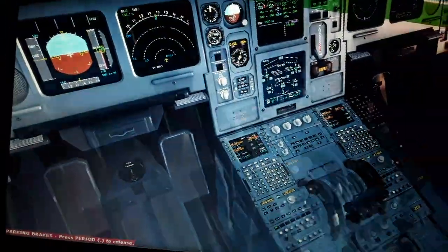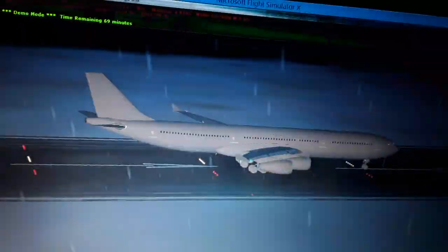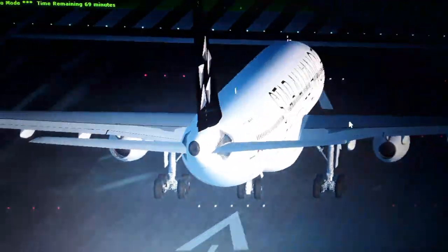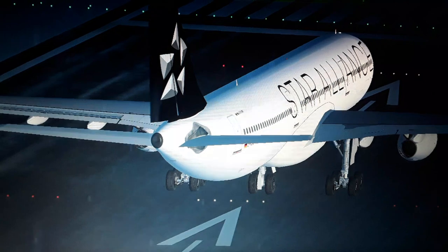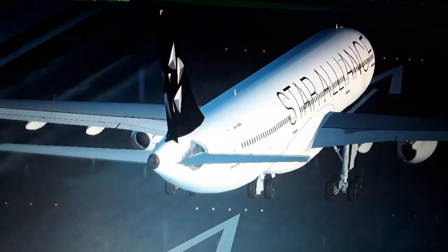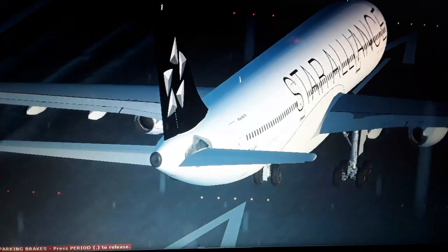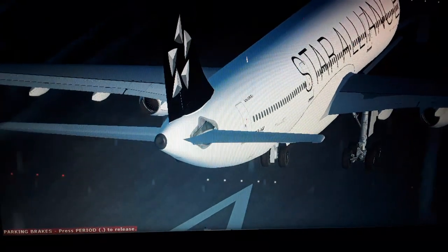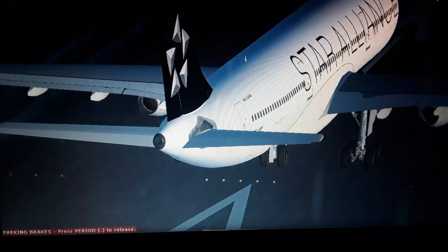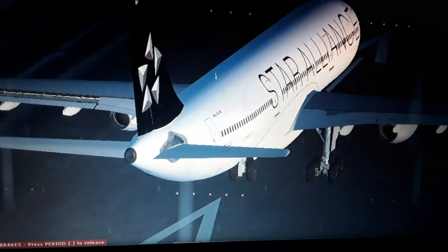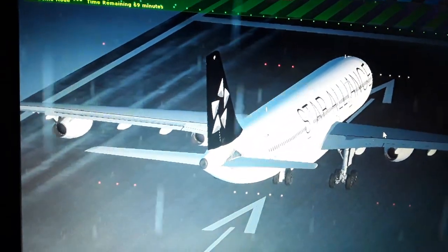When we move the side stick, it's electrically controlled, but the surfaces here, I'll show you the elevator and the other one, maybe you can see they are hydraulically actuated but electrically controlled, except for the rudder. The elevator, the pitch trim of the trimmable horizontal stabilizer where the elevator is located, and the other ones and the spoilers are also electrically controlled but hydraulically actuated.